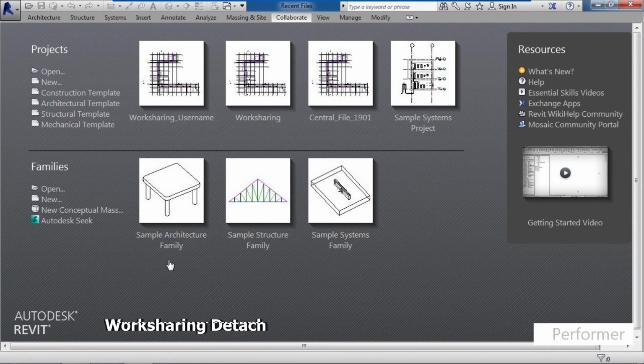Well, what you don't want to do is make a copy of the central file, and you definitely don't want to make a copy of your user file to send to the actual consultant, simply because they still have all of these shared synchronizing capabilities in it back to the central server.